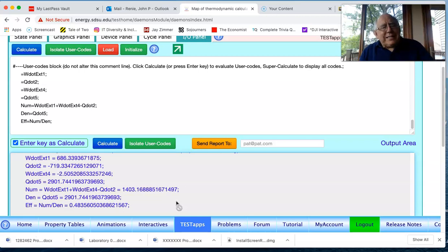And so what one then sees is almost a 50% efficiency associated with this vapor power plant. And so basically that's telling us that for every 2 units of heat that we deliver to the boiler, we're able to generate or deliver heat or power, work, electricity out of that. So that's a fairly good return on our investment. So that's the solution to this problem.